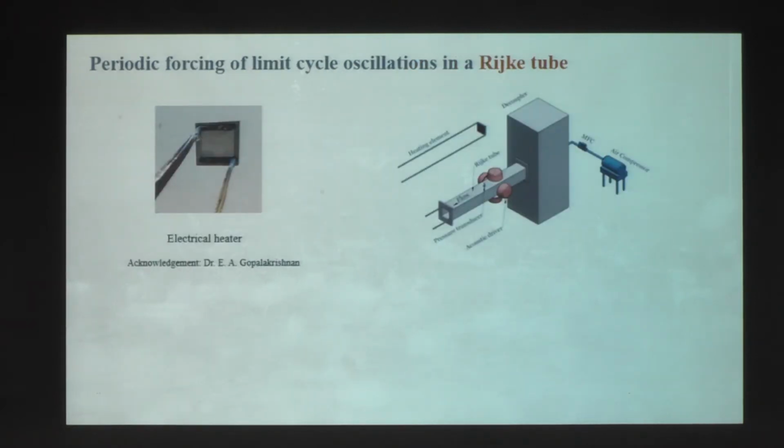So we start with this system first, where there is no flame. An electrically heated wire mesh is placed in a duct, and because of this coupling there will be sound, so thermoacoustic instability. With this setup we are not changing any parameter related to thermoacoustic instability. We are positioning the heater and setting the flow rate, etc., so that we have thermoacoustic instability. And then there are 4 wall mounted speakers through which we are sending the sinusoidal excitation.